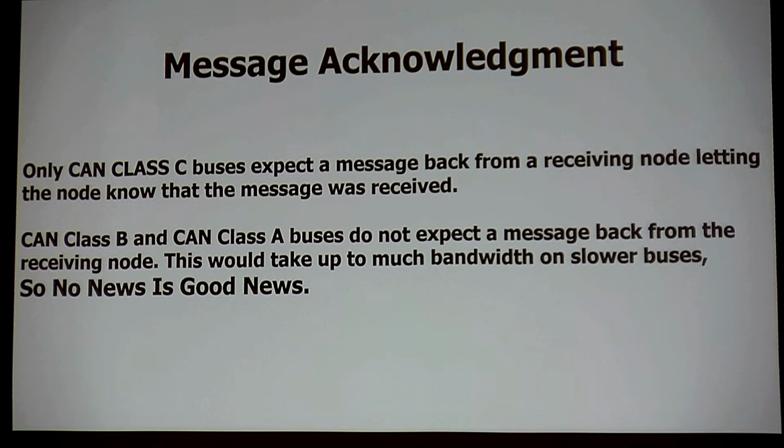You're going to see this. The guy who got control of the bus is determined that he's going to be the failure. And that is because of the way that this system is set up. So I'll get there. But you need to understand that you can have a module that died with no codes if he died all at once, and no one set any codes prior to him dying.